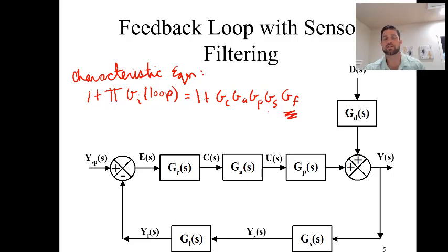In practice, what you need to know in terms of applying a filter is that we have this filter value f, a value we add to the sensor to give us a smooth signal. If we want to assess the stability or see how this filter factor affects the dynamic response, which is one of the things we like to do in theory, in practice you can figure this out by tinkering a little bit. But we can use the characteristic equation to see how filtering affects both the response and the dynamic behavior, so how much oscillation, the speed of response, etc. So we're going to do that here.